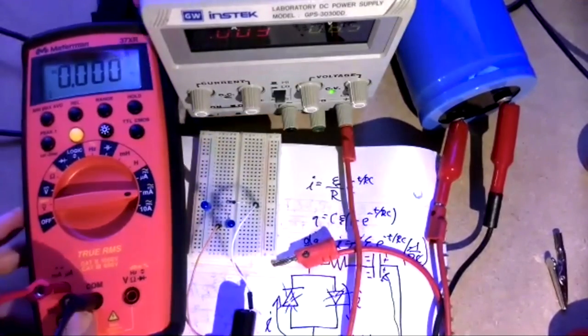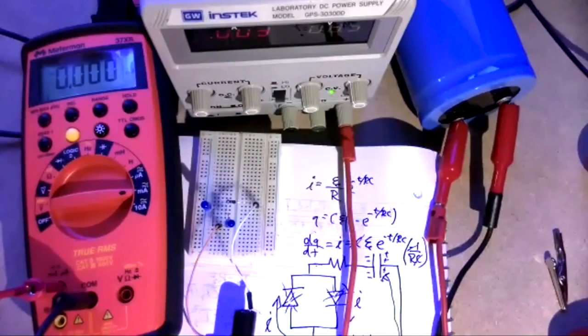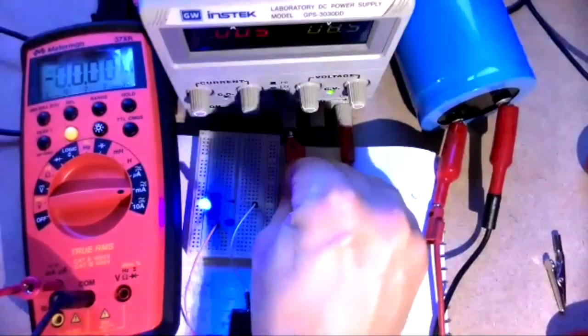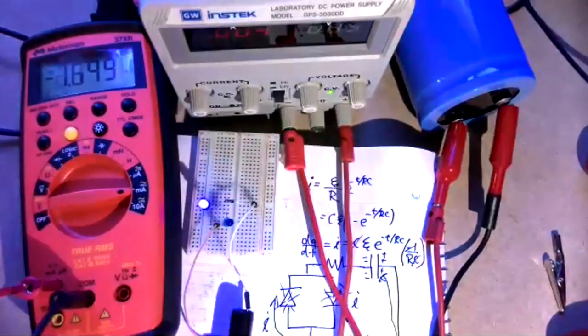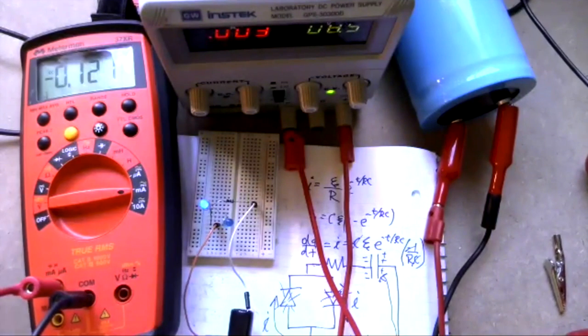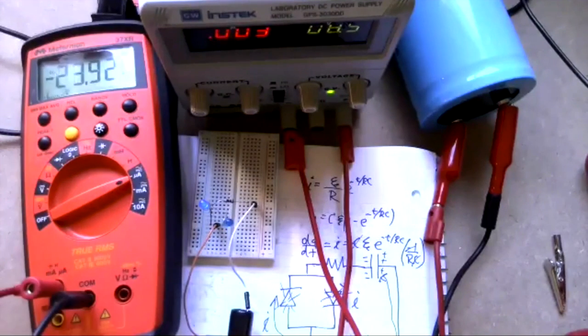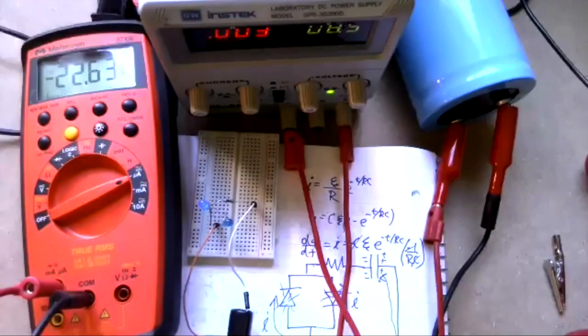There we go. Okay, and then from the other side of our current meter, now we're going to plug this back into, and look, it already started. See, that thing is glowing. Look at that. My LED has turned on, and look at my current here. It is starting to decrease. This was in milliamps, so I'm going to go to microamps. Okay, so we've got minus 22 microamps, and yes, it looks like the current is decreasing over time.